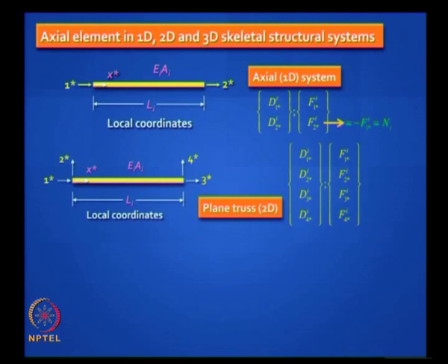Why are they 0? Yeah, so what do those force components refer to? Shear forces. So you assume that axial elements have no resistance to shear, so they are 0, and equilibrium demands that F3 star should be equal and opposite to F1 star, right.